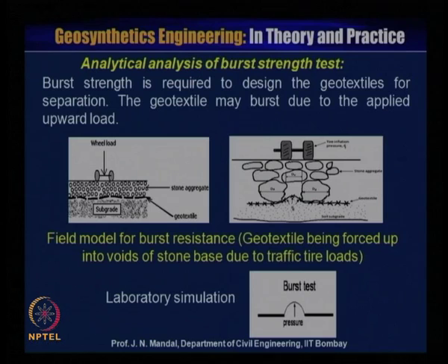Burst strength is required to design the geotextile for separation. The geotextile may burst due to the applied upward load. You can see here how you can compare the field model of burst resistance to the laboratory simulation.